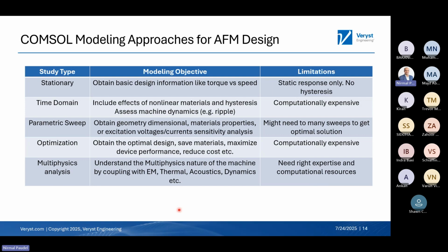Starting with the stationary study, basically we take basic information like torque and speed. The static response only, usually for the stationary study, you don't typically model the hysteresis in the motor. Then you can include the time domain where the eddy currents effect or the losses that are coming from the motion, also due to the harmonics, can be captured.